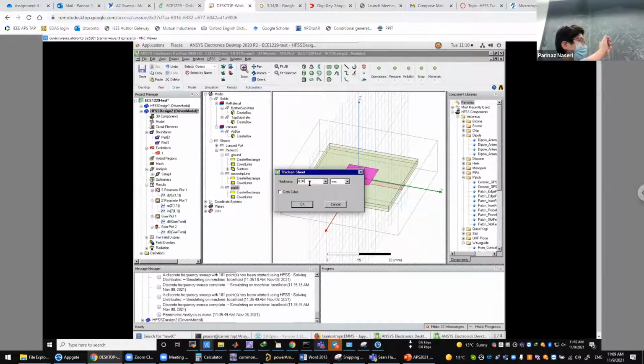But the thickness of the metallization on the two sides of these dielectrics is specified by the company. You can't go arbitrarily thick with metallization. Sometimes it's 18 micron, sometimes it's 36, or for more regular dielectrics, it can even go higher.